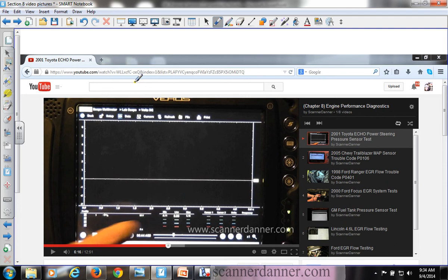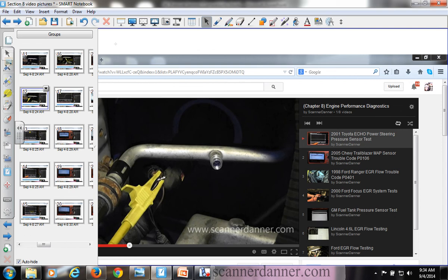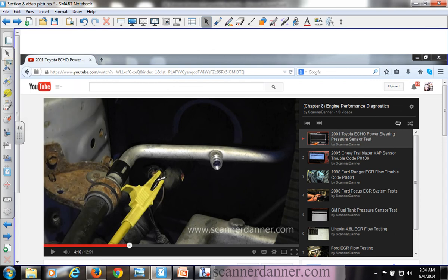I don't know if that picked up or not, but I'm recording, by the way. What is a quick way to identify which one the signal wire is? There's not a universal answer to that. What I would generally do without a diagram, Ryan, is measure all 3 wires, and based on what I see, make that determination. Now, in this case, I have 2 wires that read 0 volts. So I need a diagram to know.